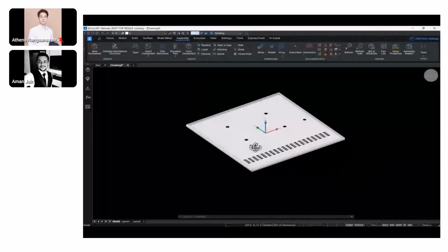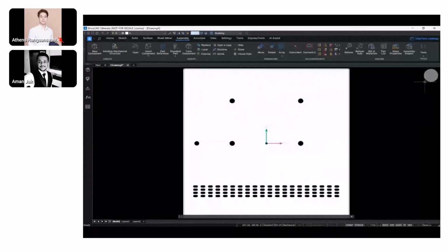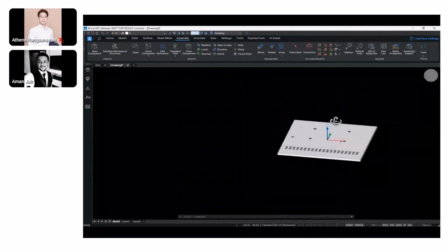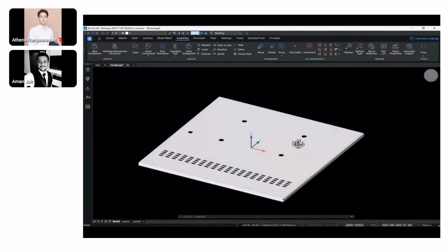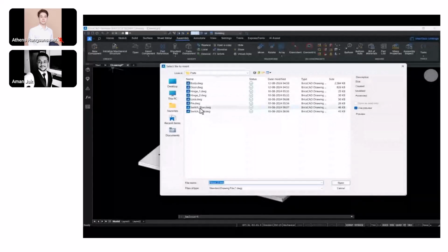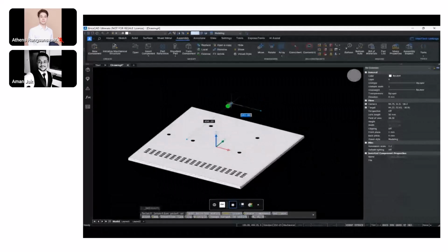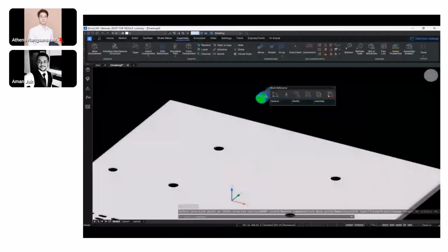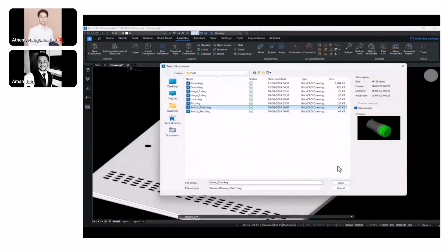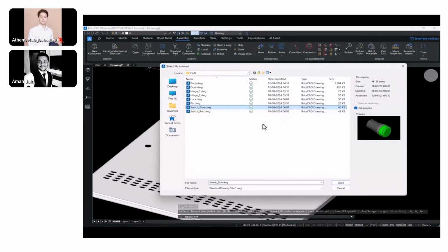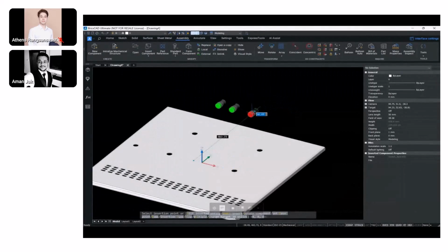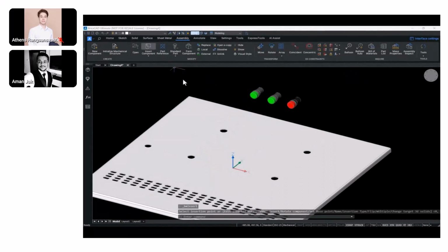And then we'll try to add more components, like I was mentioning earlier, the switches for our door and also the lock. Okay. So again, we'll use the insert component, or you can even type in BM insert on the command line, which essentially executes the same command. You can go in from the ribbon or you can use the command line depending upon the comfort level of the user. It really becomes handy for someone who's coming from a CAD background, who's very comfortable using the command line rather than the ribbons. Right? So it's really handy for them to be able to execute the commands that they want through the command line, even for the 3D operations that they do.